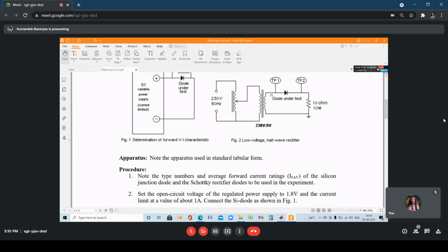Okay. So TP1 will be a pure sinusoid because the input to the system is a sinusoid, the mains power supply. So after step down, it will be another sinusoid. Clear? And then what is being done after that? We have put a half-wave rectifier circuitry. So what appears at TP2? At TP2, you will get the half-wave rectified version of the waveform.